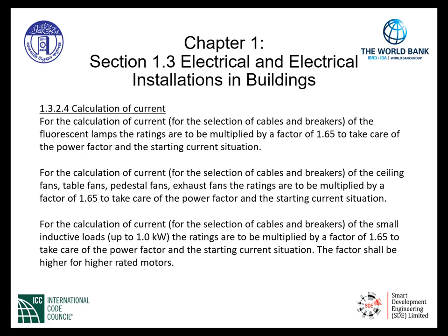Lastly, small inductive loads up to 1 kilowatt. We need to understand that the calculation of current must also be multiplied by a factor of 1.65 to take care of the power factor and starting current situation. The factor shall be higher for higher rated motors above 1.0 kilowatt.